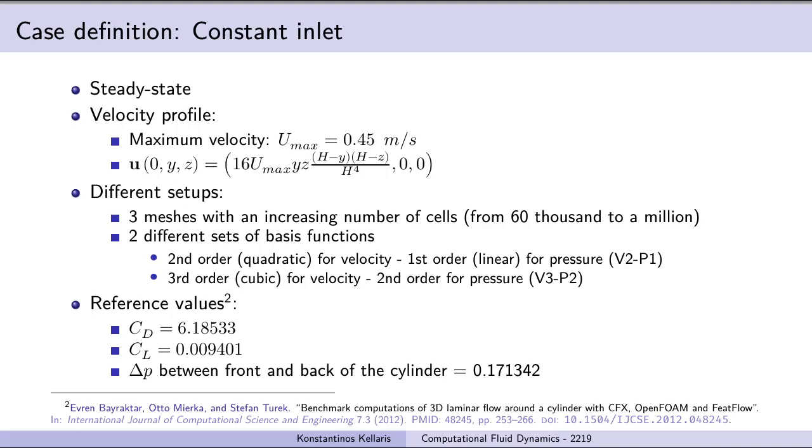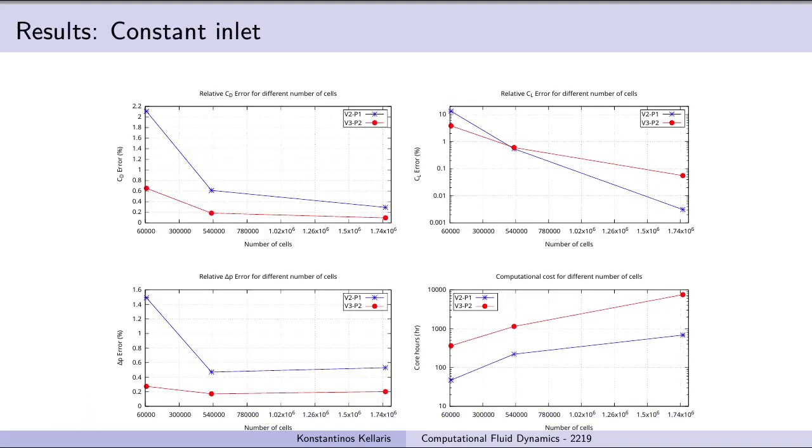The simulations were run on the University of Luxembourg ARIS cluster using 64 to 360 processors. Here we can see how the relative errors change for different mesh sizes and polynomial orders. By increasing the mesh resolution, we can see that the code provides better results but with rising computational costs. Also, an increase in element order produces more accurate results but is more computationally demanding.